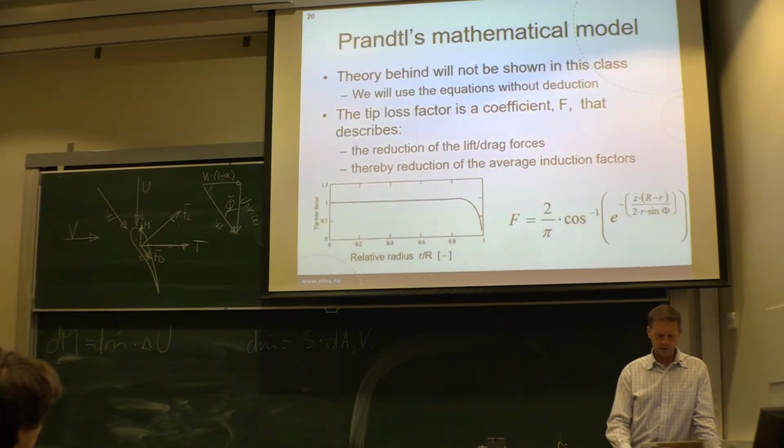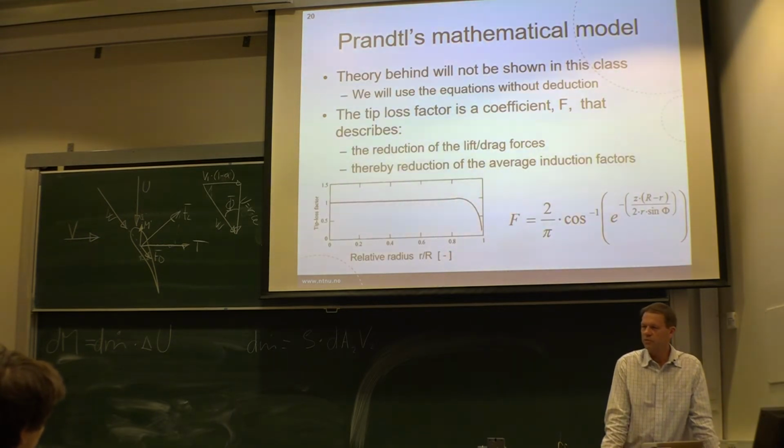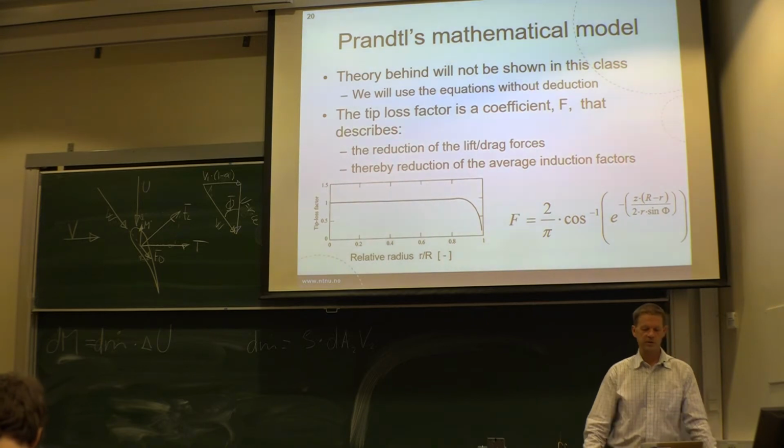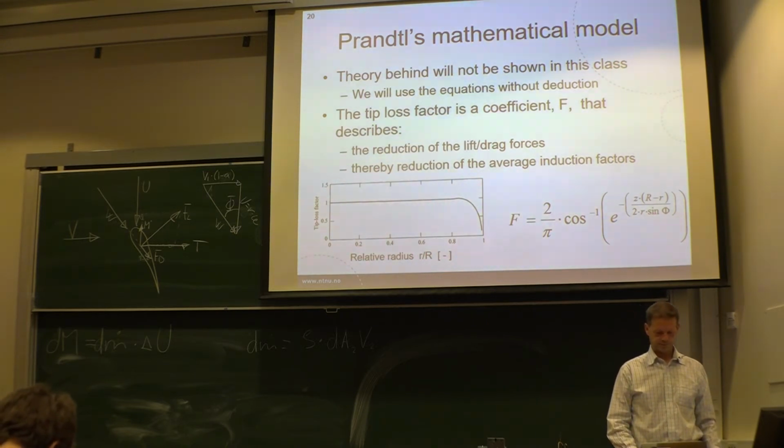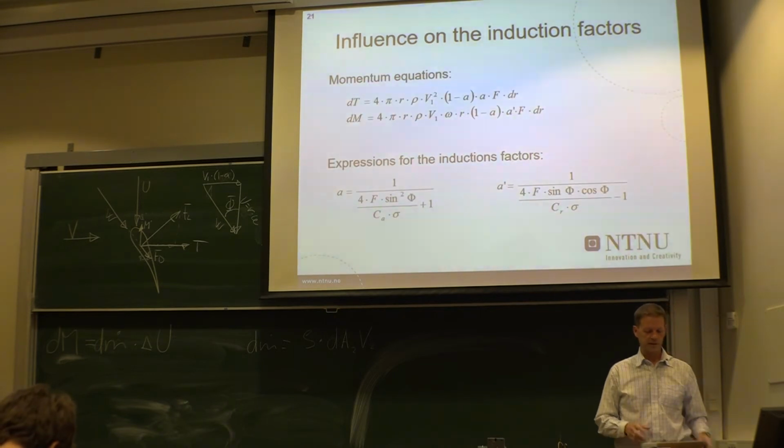In the compendium you will find equations for the tip loss factors, and it is possible to introduce that into the blade element momentum method. It's quite common to use it as well. But I simply advise you not to use it in the first round when you're making your own model. I'll come back to that later.